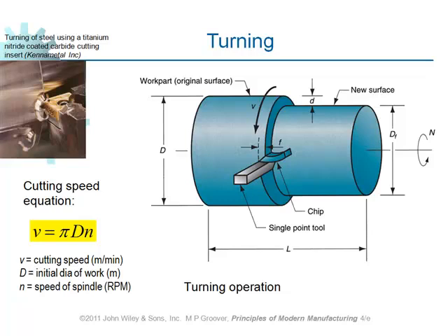And a very important parameter in any machining operation is V, lowercase v, which stands for cutting speed or velocity. Okay? What does that mean? The definition of cutting speed or velocity is the distance traveled on the surface of the workpiece. Take a look at the cutting tip of the cutter.